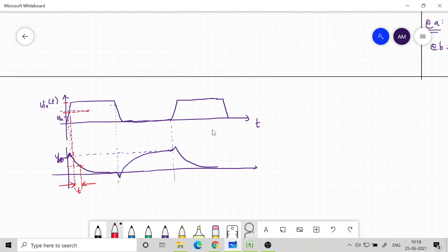This is how, earlier we have, this is also called fall time, and similarly the same 50 percentage point you take here also, and this is the 50 percentage. You see that these times are really showing up very small compared to 10 to 90 percentage. So this is T rise.